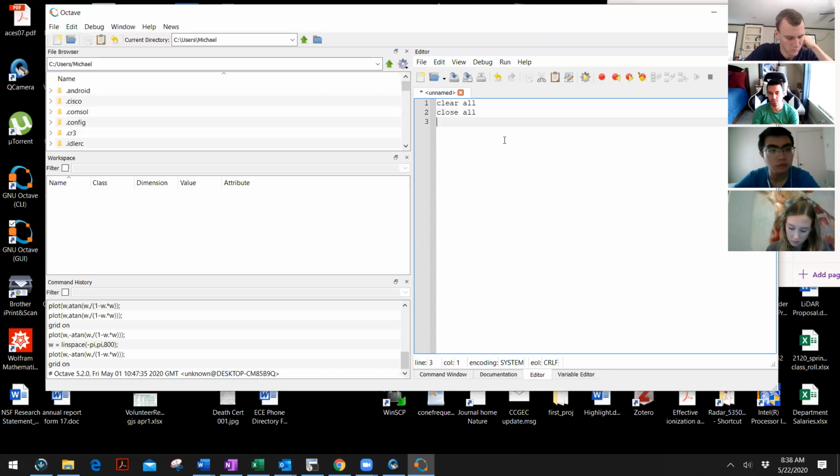And then CLC. In MATLAB, it clears the screen, gets rid of everything in memory, and it shuts down all the plots. So you have a fresh start. Then you put the values here that you're going to be using. So R per meter in this one is 1 milliohm, so 0.001. Then C is equal to 2e to the minus 12, that's 2 picofarad.